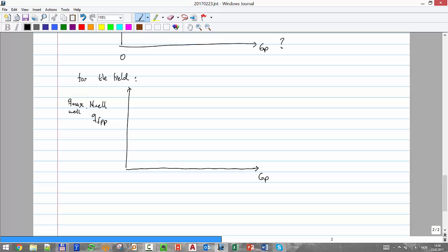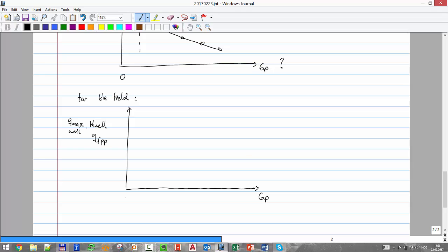Of GP. So now I'm going to ask you something a bit tricky. How do I calculate this GP? Does it depend on the well production, or does it depend on the field production? Field. On the field production, right? So this GP is all the time calculated with the field. Okay, and let's say the curve for dry gas, that's the actual shape. It looks more or less like a straight line.